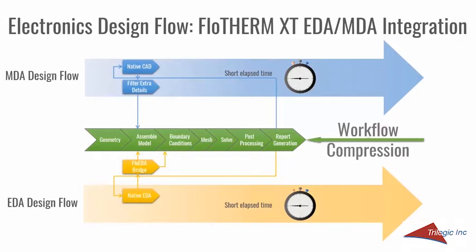Also, previous settings are retained by FloEDA Bridge, so EDA design updates can be re-imported and any previous simplifications to the MCAD geometry can be repeated before the geometry is re-imported into FloTHERM XT. So the simulation model can keep pace with the changes in both the MCAD and EDA design flows, hence the subsequent simulations can be undertaken even faster.